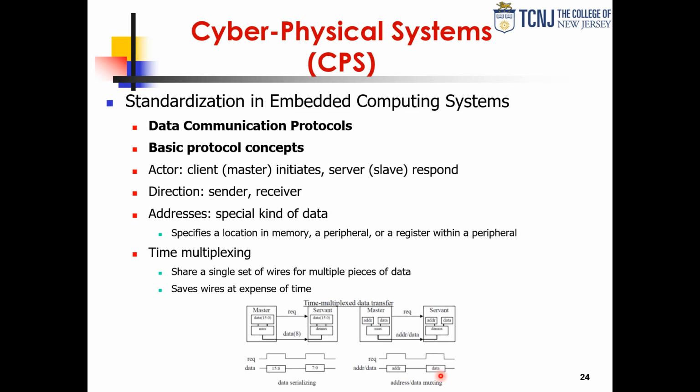That transaction becomes a bus cycle, which may take many clock cycles. That is a bus cycle, because that's what the transaction is. You need the address and the data to affect the transaction, whether it's read or write. So that's the distinction between clock cycles and bus cycles. A bus cycle is what it takes to affect a whole transaction in a communication between two communication entities.